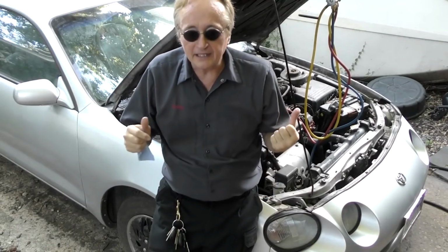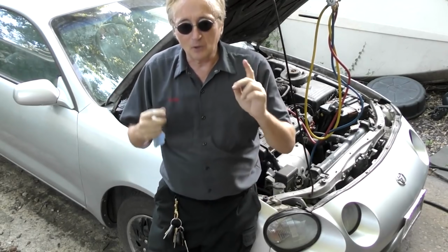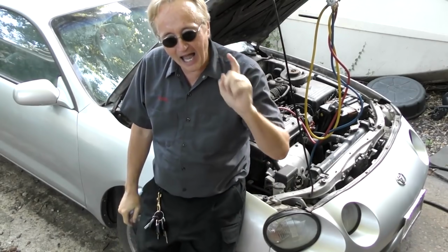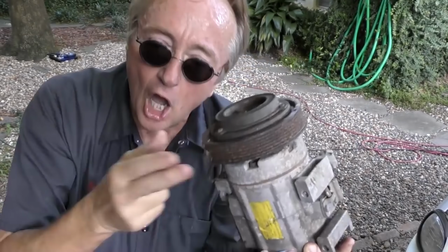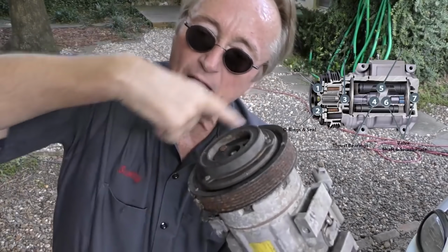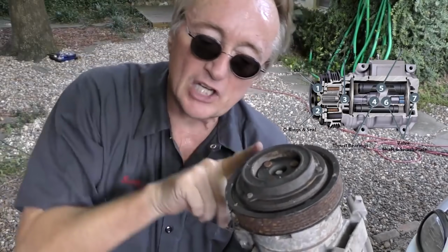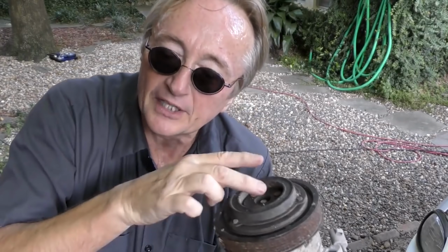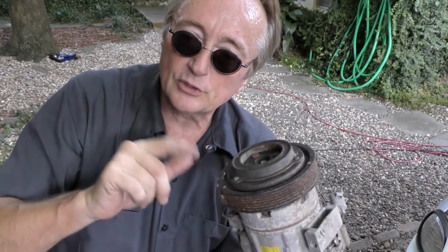Now this may be a 26-year-old car, but I've only had to add refrigerant one time. Now here's an old broken AC compressor. All air conditioning compressors leak somewhat over time. The fan belt spins the shaft. The shaft has to have a seal on it. If that seal was perfect, it would run dry, burn out, and all the freon would leak out. They all leak a little bit of refrigerant and AC oil in order to lubricate that seal.